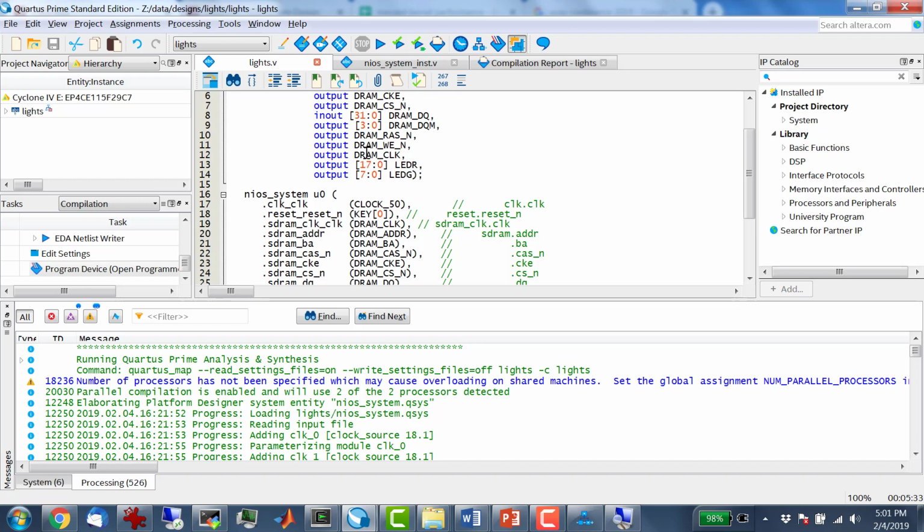And one of the things you'll notice is that I use a usleep in that code, which puts the code to sleep, just a busy loop, while it's waiting. That's put in there to slow it down so you can actually see the light moving. The problem with that is that it makes the buttons a little unresponsive, because if you push the button down while it's sleeping, it may not see the button push. So you'll notice that when you want to change modes, you have to hold down the button for a little while. It's not real snappy. It won't respond to just a quick push of the button. Is there any way to fix that problem?